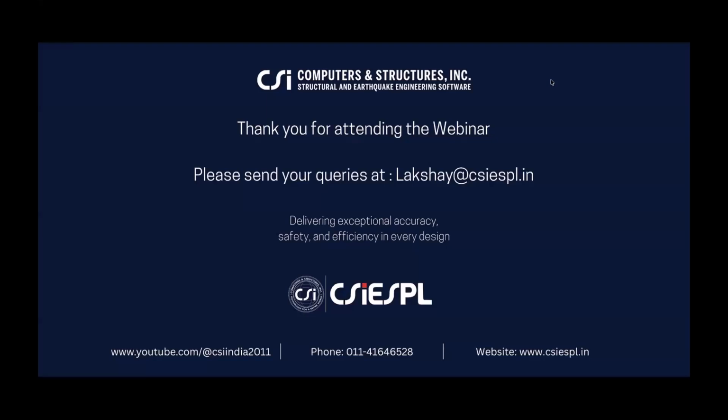You may find this exercise too long, but since I have introduced a very new concept, it might feel so. The bifurcation is the only key thing that we are going to do: one is for the lateral force system and another one is for the gravity. When you practice it, it actually doesn't take much time, except for updating the load combinations and a few other things, like the definition of load cases and hinge assignments. But this exercise is required.